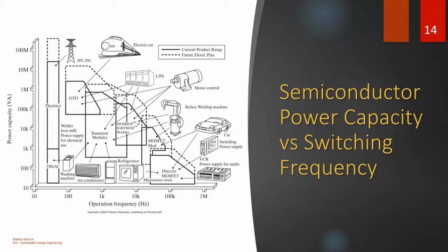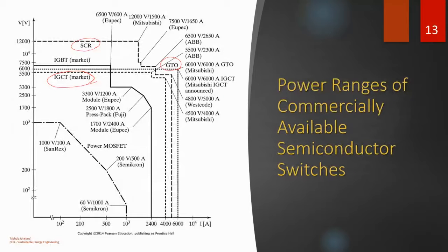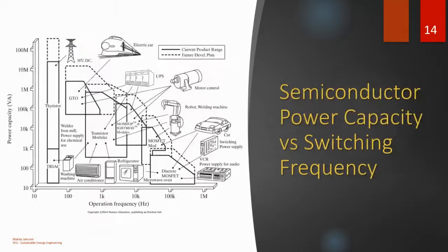If you have a hose at hand, you can create some kind of a switch that could switch it 10,000 times a second. But when you're dealing with thousands of amps, like 6,000 amps, you should not expect to be able to switch 6,000 amps 10,000 times a second. You might be able to switch it 100 times a second, but no more than that.